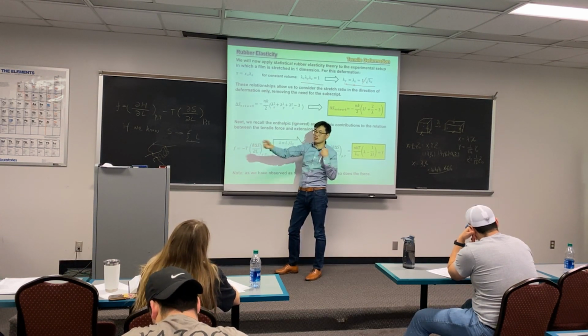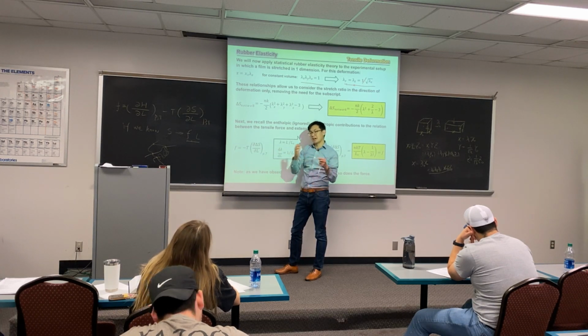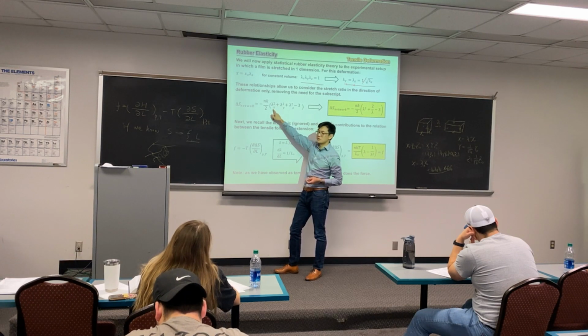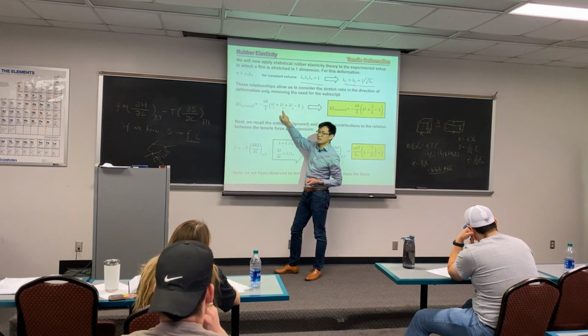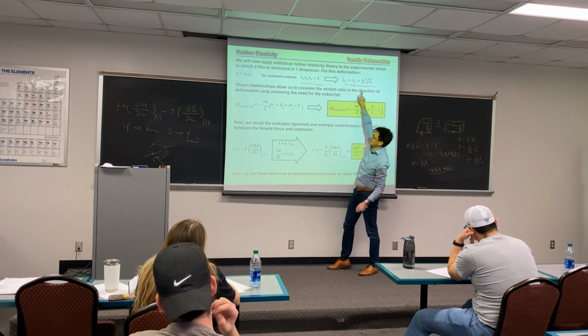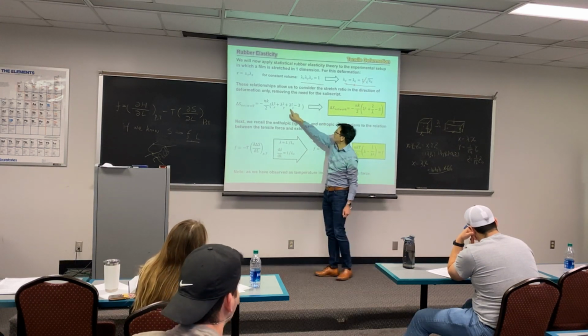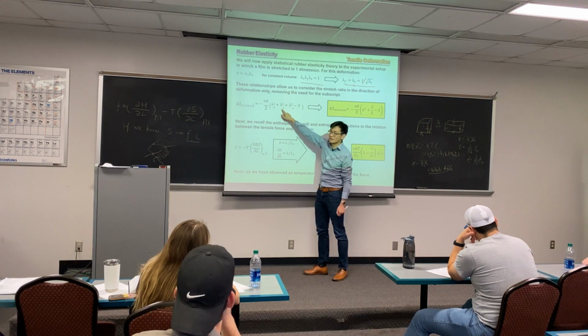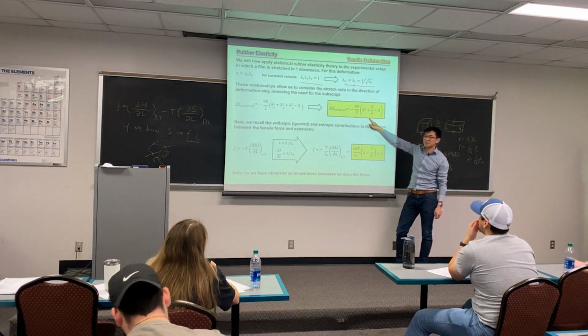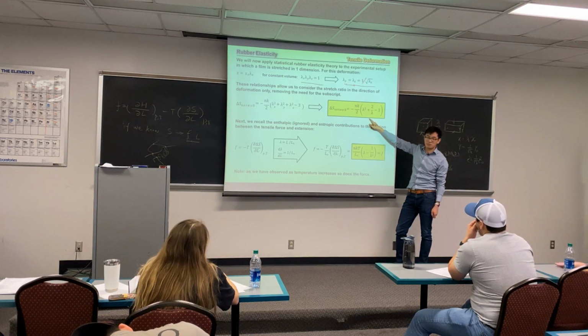It will be just equal to how much you pull. If I have an elastomer and I draw it to twice the length, this will be 2. Lambda y, as we show here, will be 1 divided by the square root of lambda x. Lambda z, same. So everybody gets why. Now we get a different description.